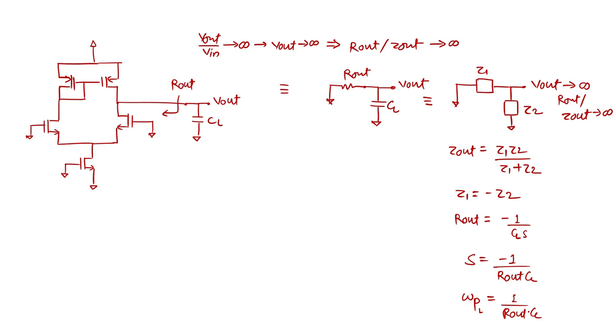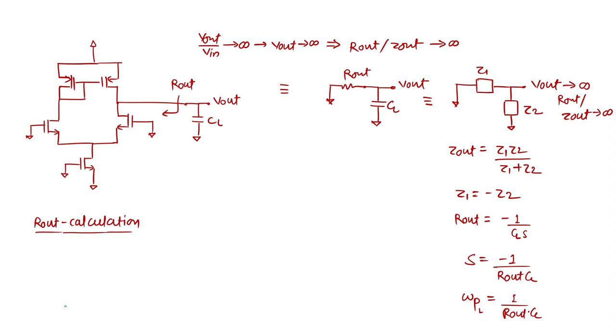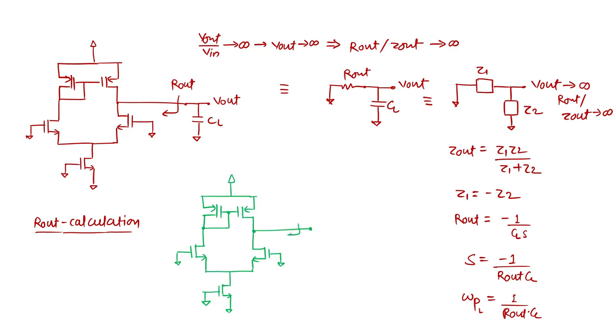So this is the one pole we calculated here. So what is the R out for this structure? Now you see the R out calculation. Many of you may have a direct answer for it, but I'll go for the calculation because some people already told me to go through the proper calculation. Where there is a possibility, I will take a shot. Otherwise, there is a proper calculation for it. So now I will consider the structure. We will calculate R out from this point, from here.